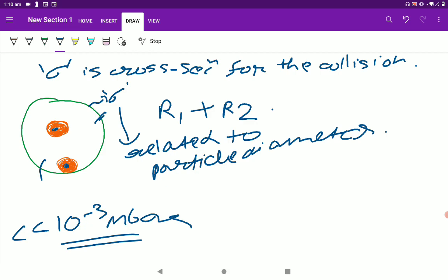We know that the atmospheric pressure is roughly 1 bar, and we are speaking of reducing the pressure below 6th order of magnitude of the atmospheric pressure, which is not an easy task. So according to this interaction, we can differentiate two main flow regimes, and that is molecular flow and viscous flow.